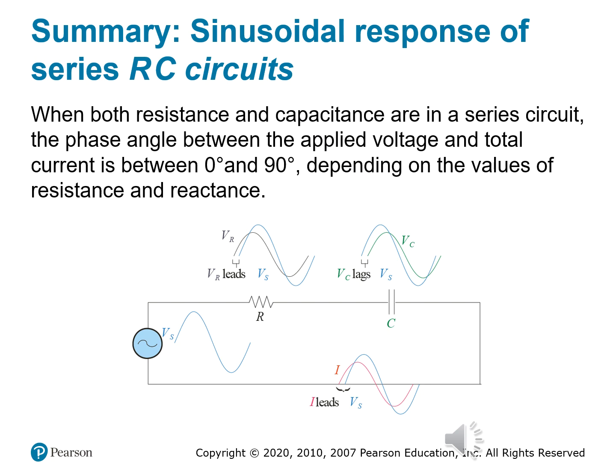So compare it to the series RL circuit. Back when we discussed series RL circuits, remember how the inductor made the current lag voltage? Well, now the capacitor flips the story. The current leads voltage. It's a mirror image of the inductive phase shift. So instead of holding the current back, capacitance lets it run ahead. On your oscilloscope, you'd spot a current waveform peaking before the voltage waveform.